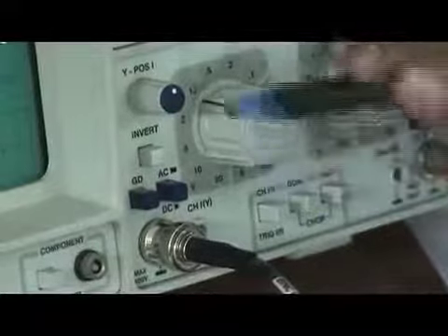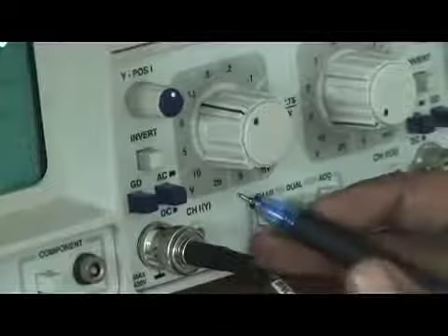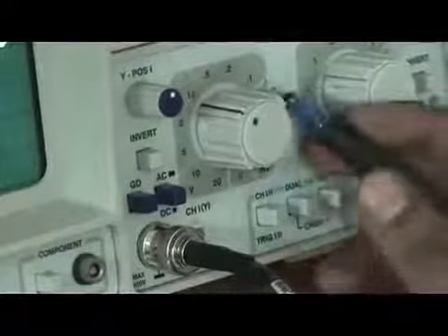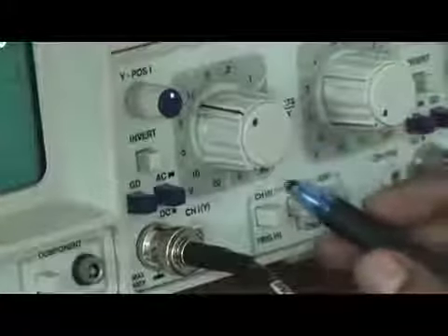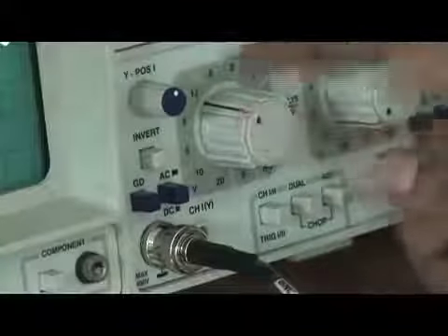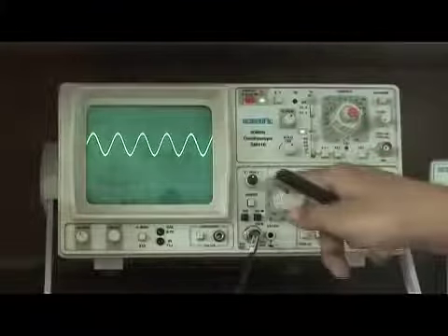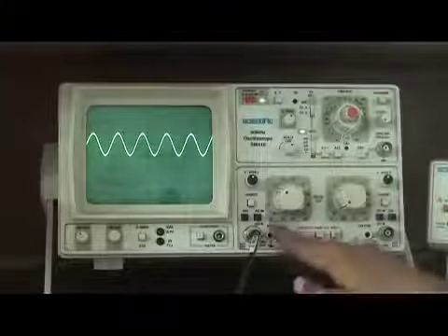From this gap to this gap, there is no other unit except some numerical values. There is only one unit called V, meaning volts. From this gap to this gap, there are various numerical amplifications, but there is one unit called millivolts. Whenever this knob lies in this range, the unit will be millivolts. When this knob lies in this range, the unit will be volts. So 1.9 blocks into 1, that is 1.9 volts.